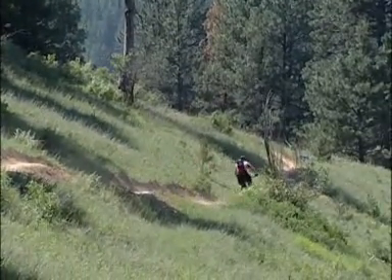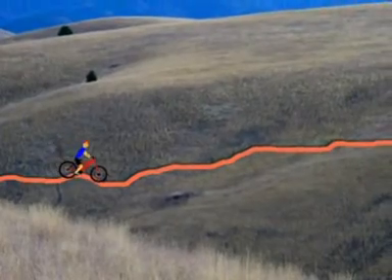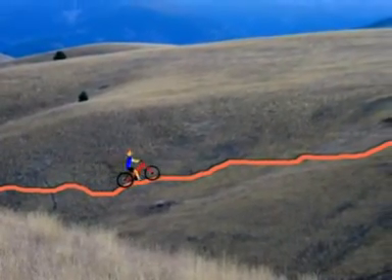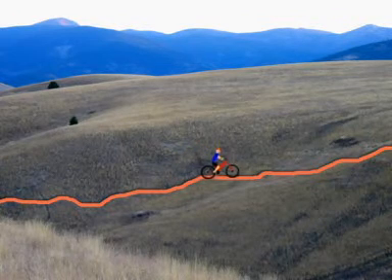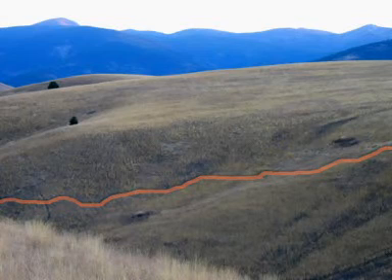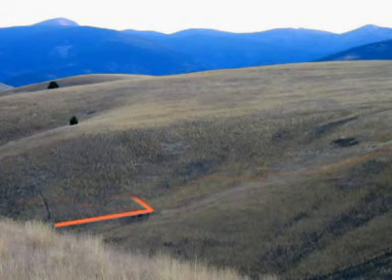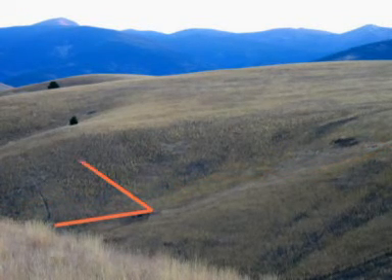But you may be saying, how am I ever going to get to the top of a steep and narrow hill using that 10% overall guideline? You're right, you can't if your trail goes in a straight line. Most contour trails require direction changes or turns to help them gain elevation at a sustainable grade.